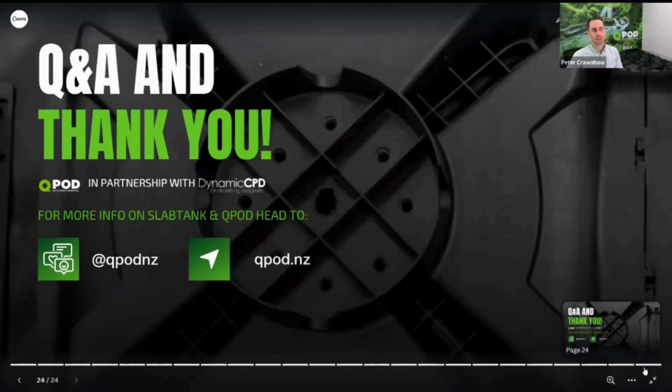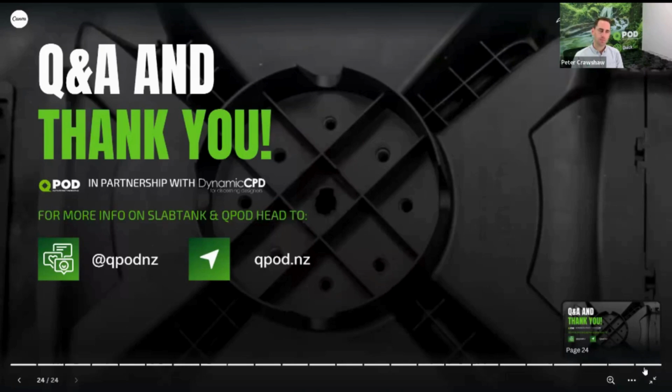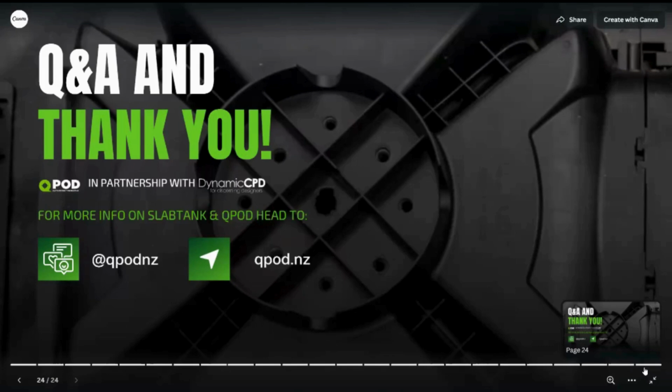100%. Yeah, and that is a challenge. You've got tanks under your concrete floor. You've got some brace walls. You've got some hold down bolts. And typically they're always going to be on thickenings that are allocated in the slab. But I have heard, obviously, when you're going to tilt up or brace a wall temporarily and put a bolt through the floor, you go sticking that through too deep and into a tank, you'd be very disappointed. The measure there is to be aware with the builders to mark out those areas where the tanks are and really take those precautions.